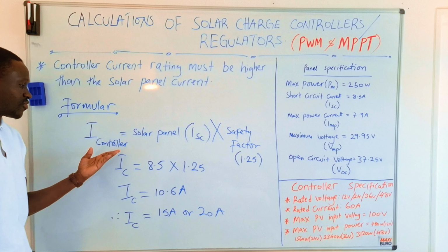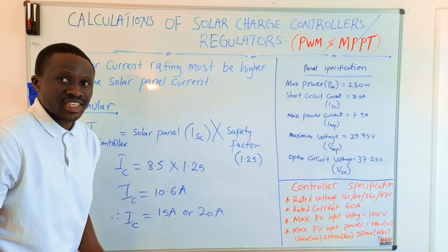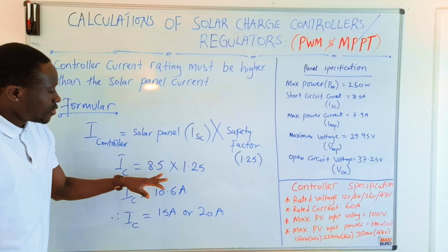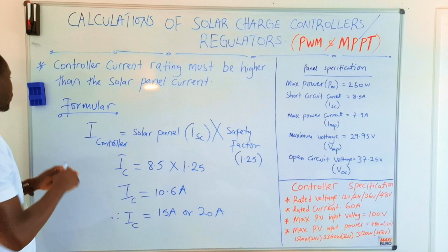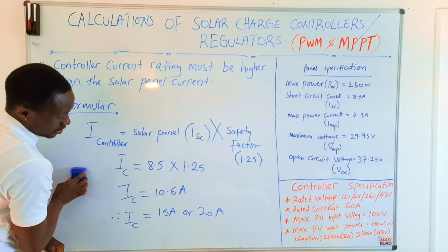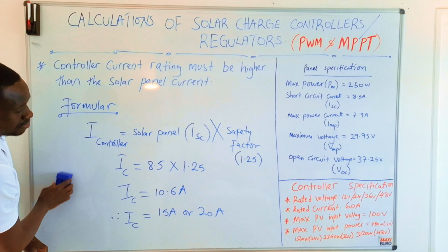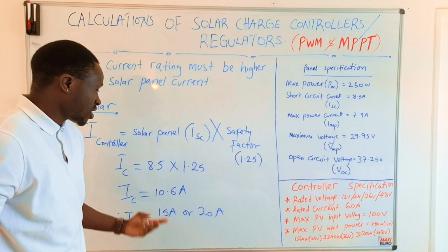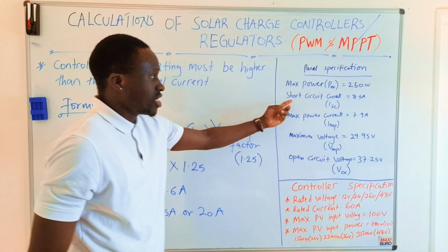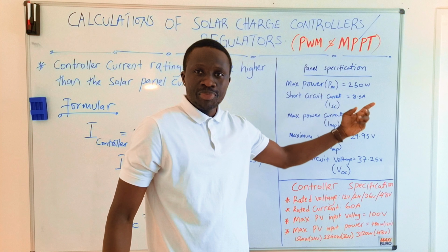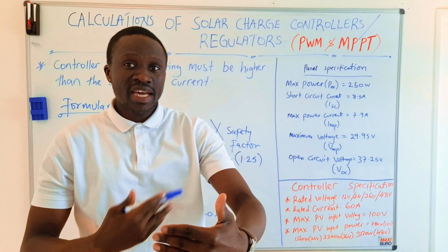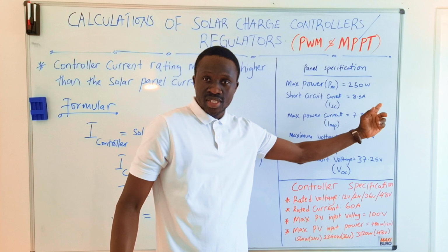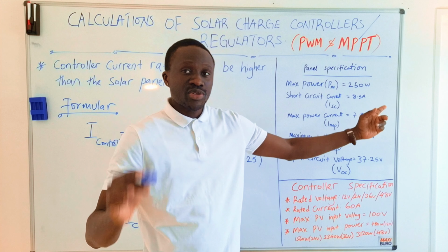Only this formula you can manage to do a lot of things. You can also do some examples. Change the short circuit current. Always see the panel behind and read the short circuit current, which is what we are going to use when you're calculating your regulator.